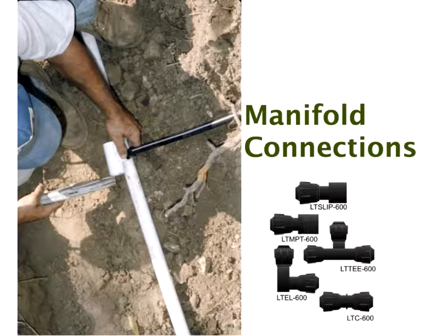If you dig it up, cut it here, and cut it there, and take a coupling like this, you can put the coupling in there and connect up a new drip line if necessary. And again, that sort of thing is extremely infrequent. But it's not difficult to do as necessary.